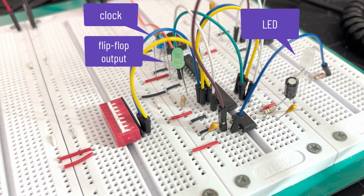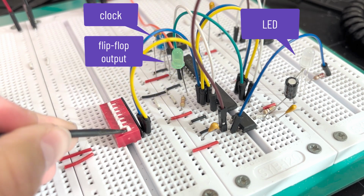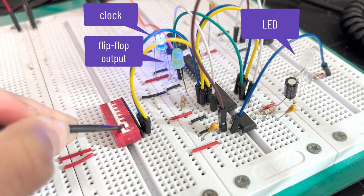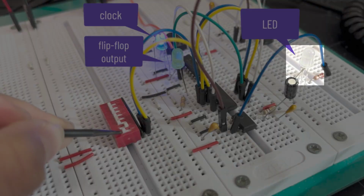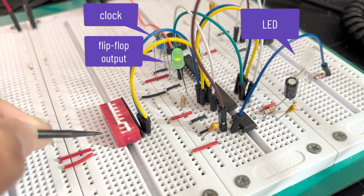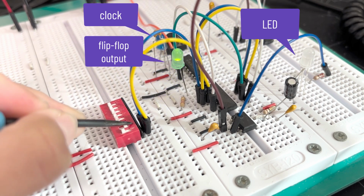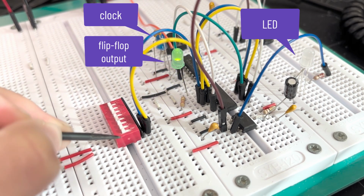I wired this up using the 74112 JK flip-flop chip, a dip switch for XY, and a function generator running about 1.5 Hz for the clock. A push button was used to asynchronously clear the flip-flop and put the circuit into the reset state. I can confirm that the circuit follows the state diagram as expected.